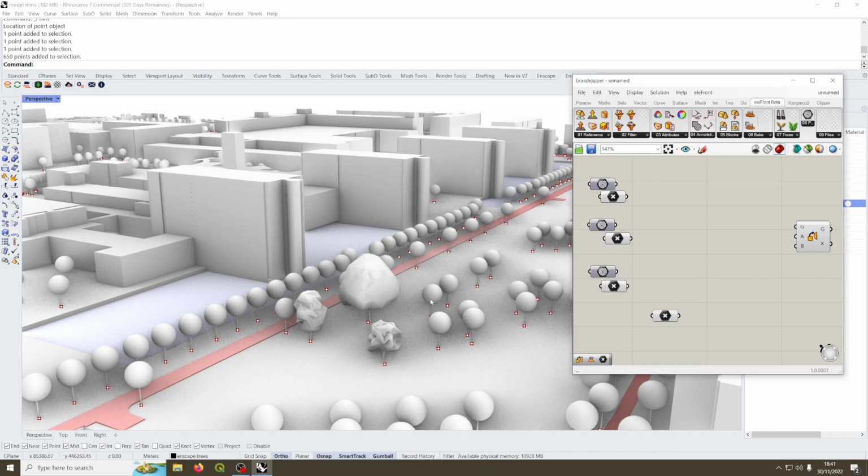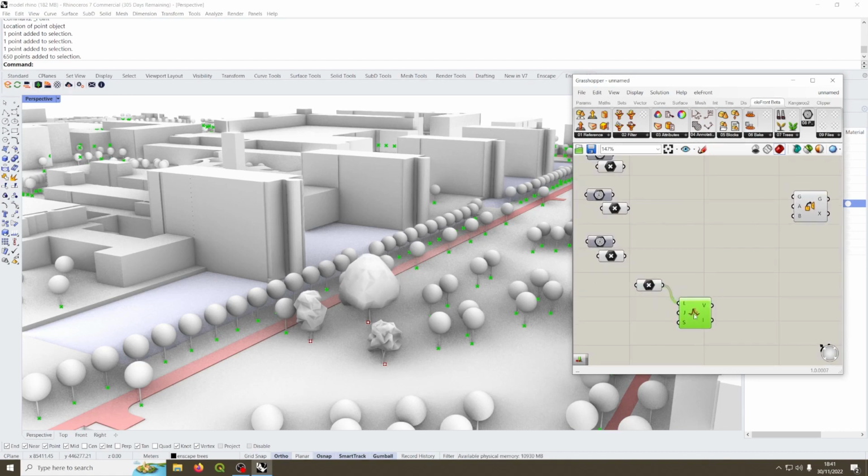We'll start off by shuffling our points. So double click and look for the jitter component and just connect it to the L input. And now we have to make 3 different sublists that each contain 1/3 of the points. So double click and look for the partition list component. And it needs a list as an input, which is our points. And it needs the size of the partitions.